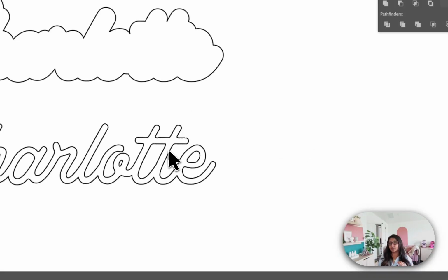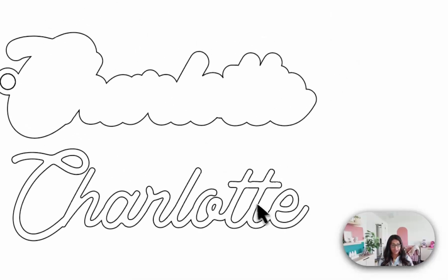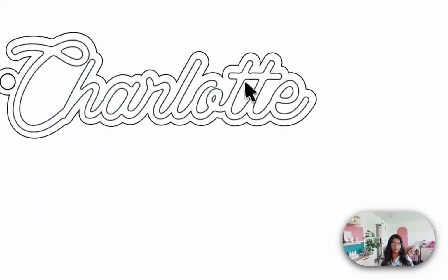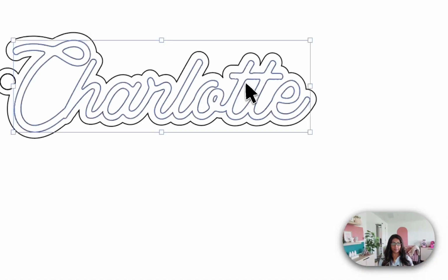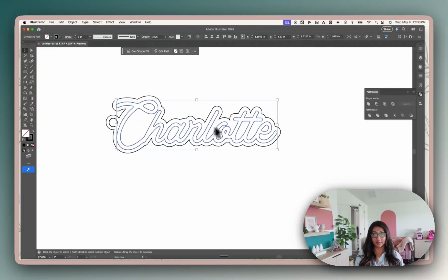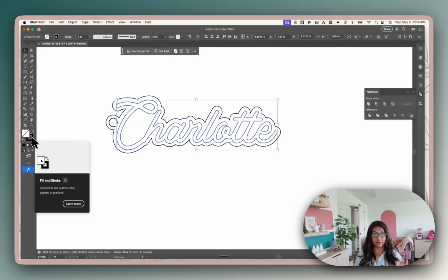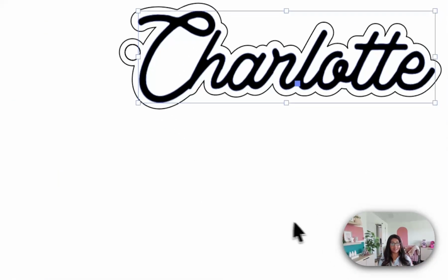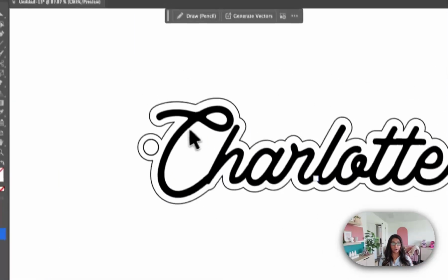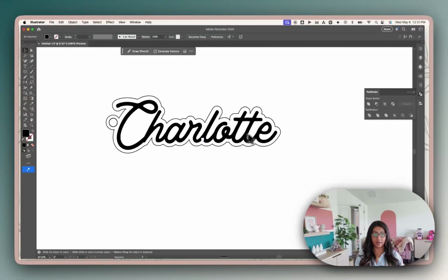Okay, now if you prefer to engrave the name in your offset over here, then all you really need to do is plop that right in here. Then you're going to swap this from a stroke to a fill. So when we did that earlier, we swapped it from a fill to a stroke. Now we're going to do the opposite and swap it from a stroke to a fill. And so when I send this to a laser, my laser is going to know, okay, I want to fill in all of these dark spots, and then I'm going to cut around all of this.